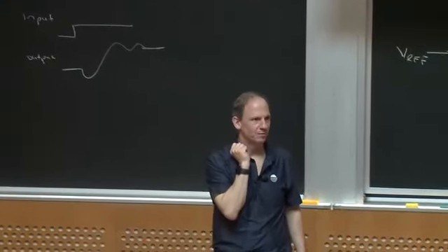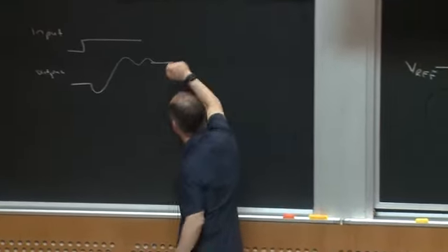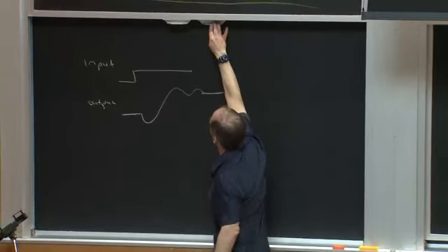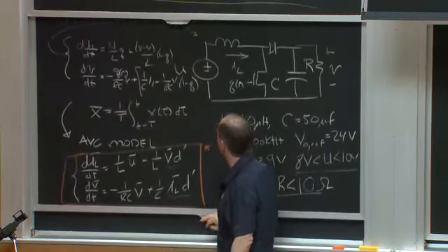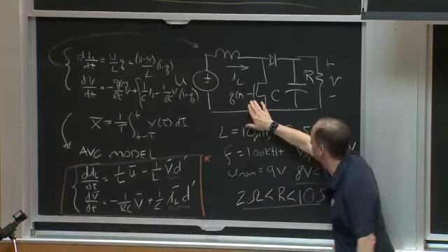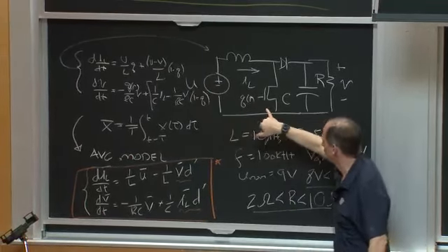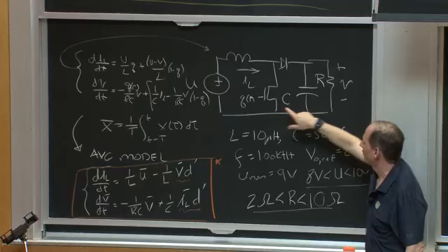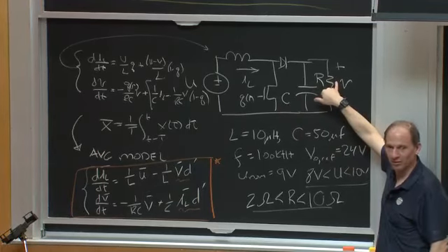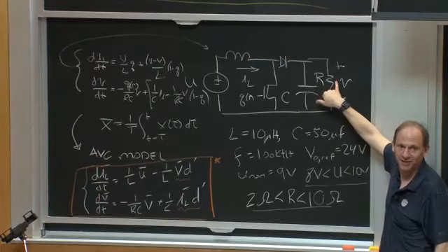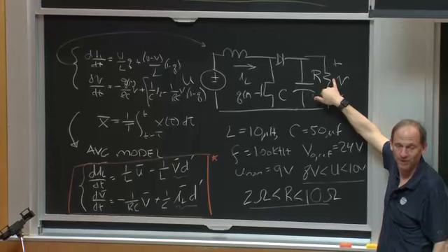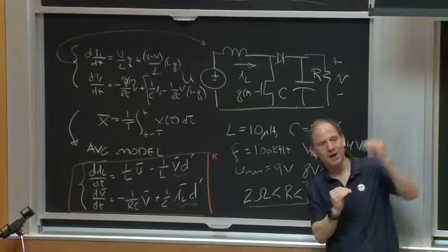And this system's like that, but I would argue that this system's like that because of the way the system behaves. Suppose I wanted to make my output voltage bigger, right? Forget about closing the loop. Suppose I'm running at some duty ratio. Suppose my input voltage is 5 volts. I'm running at 50% duty ratio, and so my output voltage is at 10 volts, right? But suppose I suddenly want to make my output voltage higher.